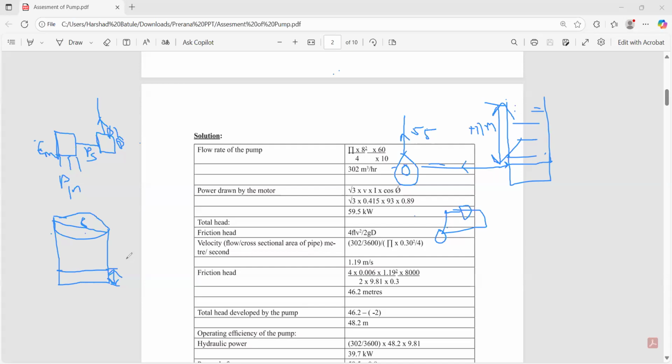To get that 50.24 m cube of water in that particular tank, you would require 10 minutes. They have given the timing. So I'm just seeing this solution itself. Pi d square by 4, and then 60 minutes divided by 10 minutes. No, don't look at that solution, I'm solving in a different manner. Okay, done. So your volume would be 50.24 in 10 minutes, right?